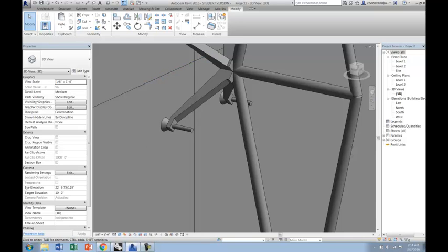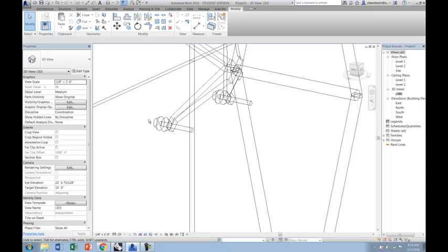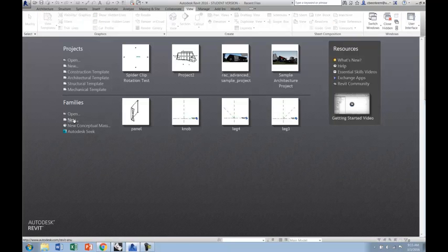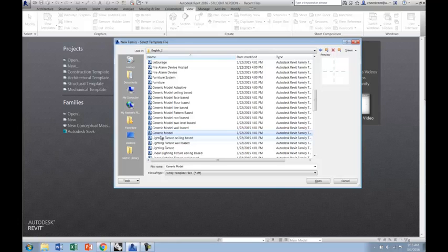So the first thing we're going to do, and if I turn this to wireframe, is one of these small knobs with the threaded rod through it that is actually the brace for holding the glazing. To start that, I'm going to go to View, User Interface. We're going to use generic models every time. So I'm doing a new family and just going to go to a generic model. We're going to use this for almost everything.